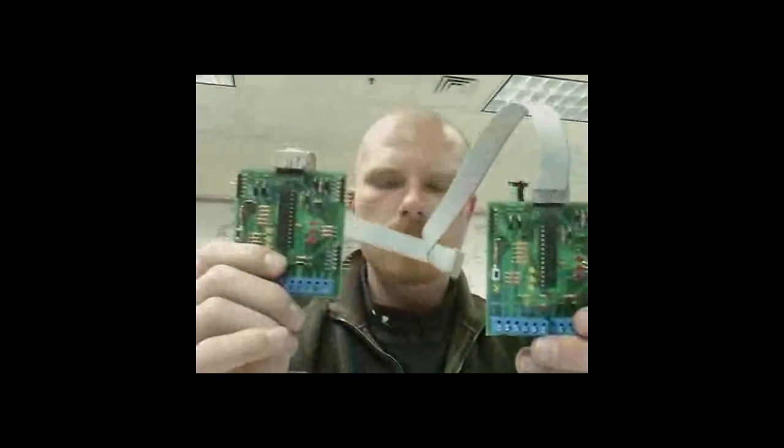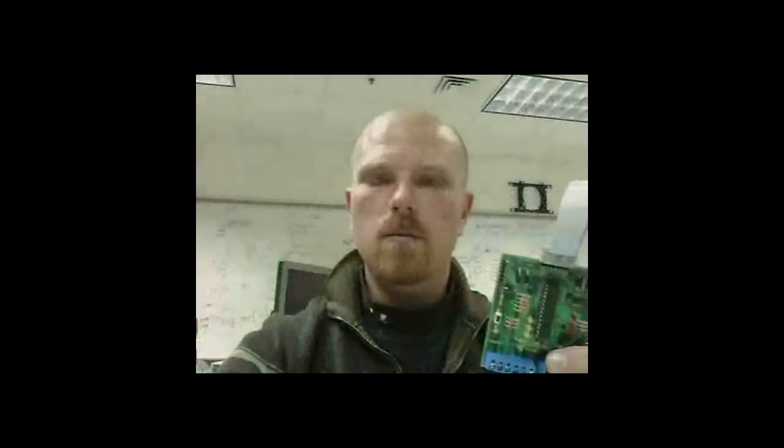We had one master PIC and one slave PIC, which communicated over an I2C bus. It's slightly different in our case because this bus is actually what we call the train bus and allows for communication over longer distances. However, the basic idea is still the same. There's one clock line and one data line, and this controls how the devices communicate.